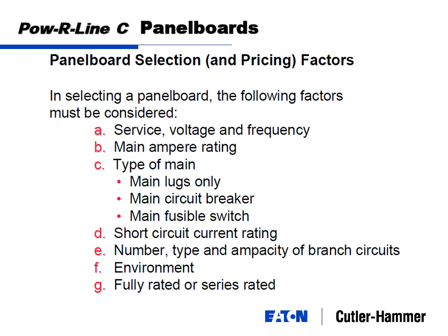The good thing to remember is that a NEMA 3R rating only prevents intrusion of water coming down from the sky. It doesn't prevent intrusion of water from a guy with a hose spraying the bugs off. That's not what it's for, and you need to move into a different step. So when you put a panel board or even a switchboard outside, there are other precautions you should take along with a NEMA 3R type rating.